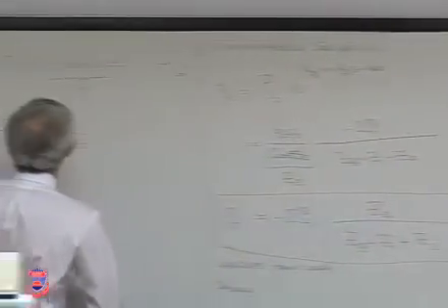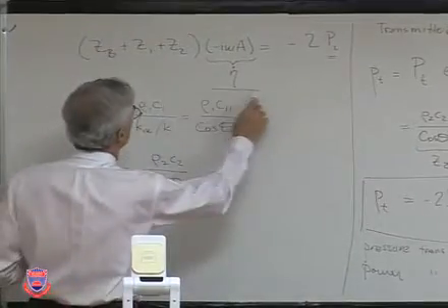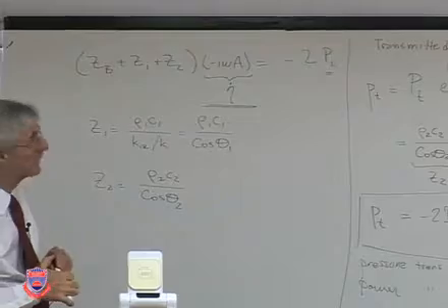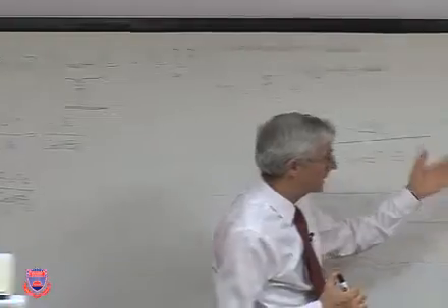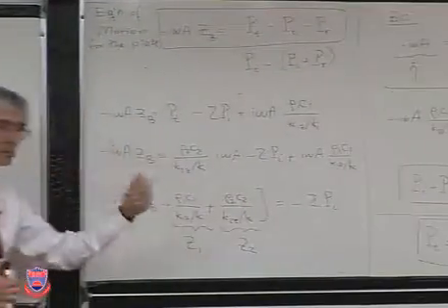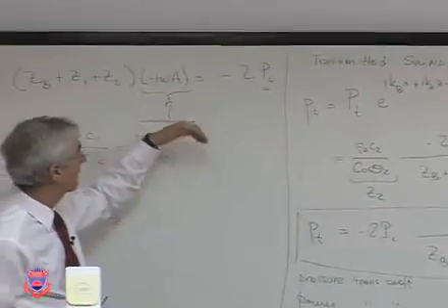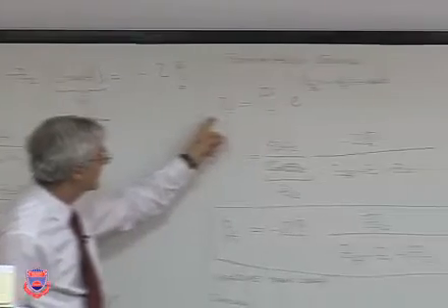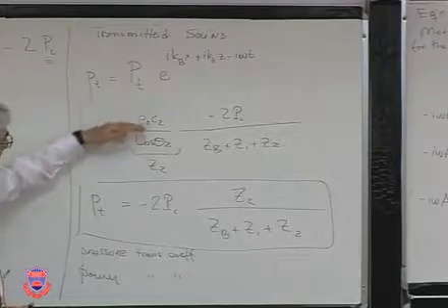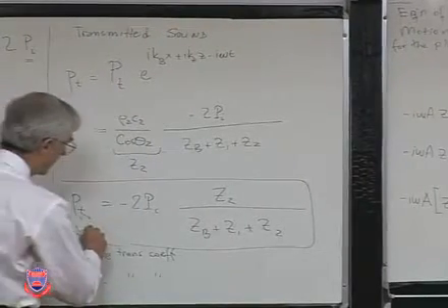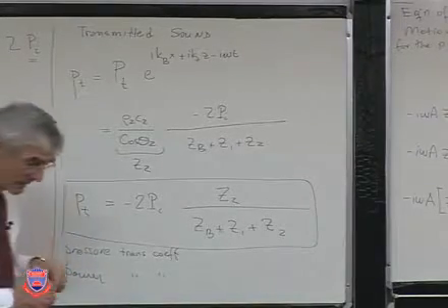Once we substitute all of those, we now have an expression for the amplitude of the plate vibrations. Now, depends on what you want to do. If you would like to get the expression for reflected pressure, transmitted pressure, we have all of these in terms of plate amplitude and the total impedance. So in this case, the transmitted pressure expression, we write it, and we have now this very nice compact form expression.